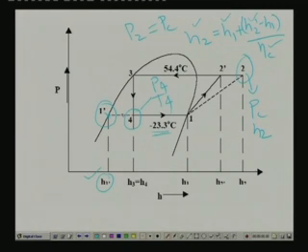That property is enthalpy, because we know that this process is a throttling process. So, for this process H3 is equal to H4. So, H3 is known to us, that means H4 is also known to us. That means at this point we know the pressure PE and we know the enthalpy H4. So, from these two properties you can find out the rest of the properties like entropy, specific volume and all that.